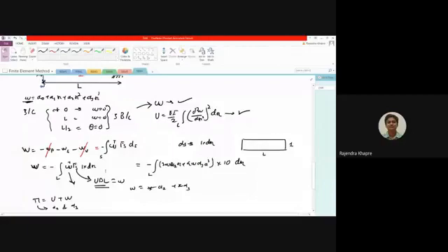Because this is your surface load. Okay, because if you convert this into point load, then you have to find out what is the deformation at that particular point. Here we don't have a point, so we have to just take whatever expression is there, the same expression you have to write down over here. Okay, so like I said, you are assuming this W over here. So whatever W you assume, after putting in the boundary conditions, the W that comes out, that W expression will be there.